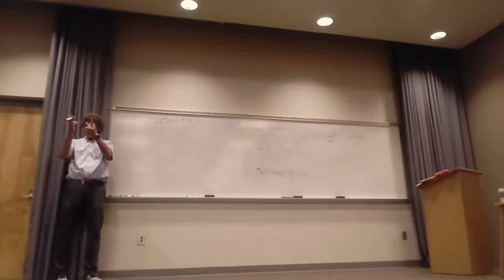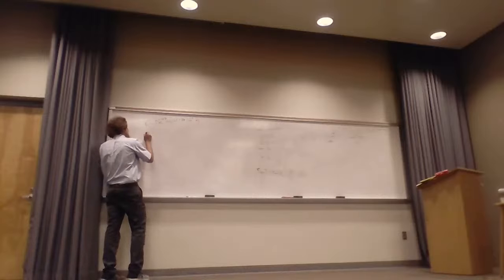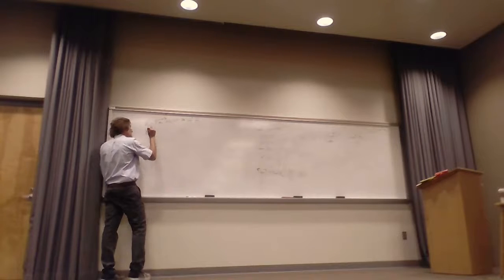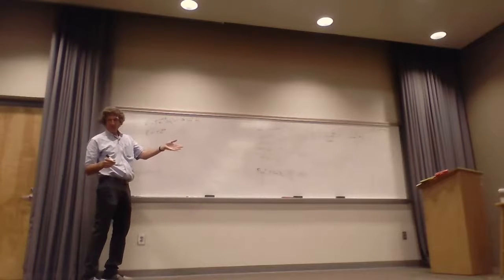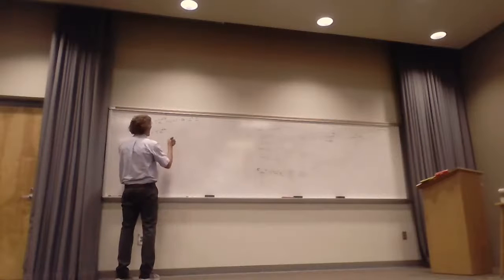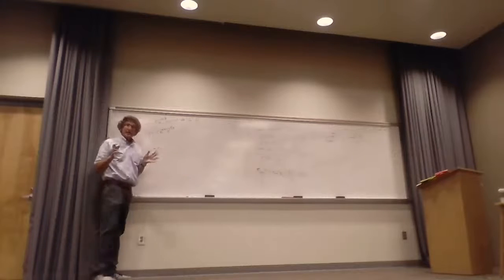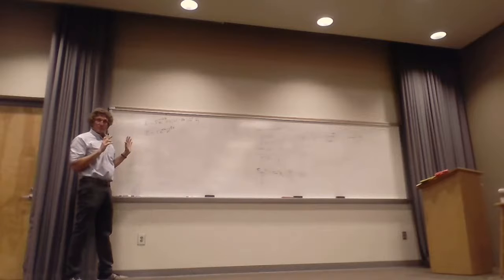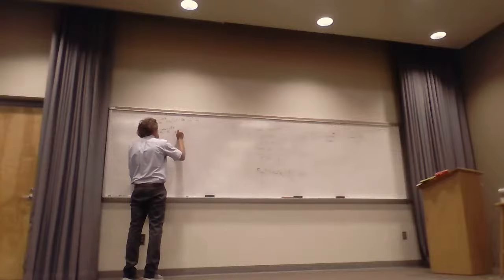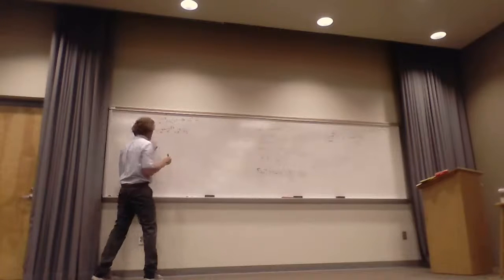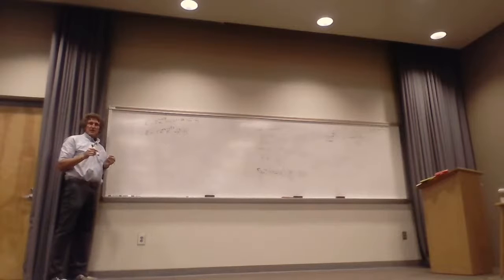Now I'm going to put it in the phasor domain, right? So the thing I do is E, and I'll put a vector phasor here, is equal to the magnitude, or I should say the real part coefficients, which is just 5e to the minus alpha z. We calculated alpha, right? About 4,000, is that right? All right, we calculated that. Now we simply put e to the minus j beta z. Beta is equal to alpha. We could combine those, but I'm going to leave them separately. We know beta is about 4,000, right? Times 10 to the minus 3 a_y. Now the default units are volts per meter, so I'm not going to write that.